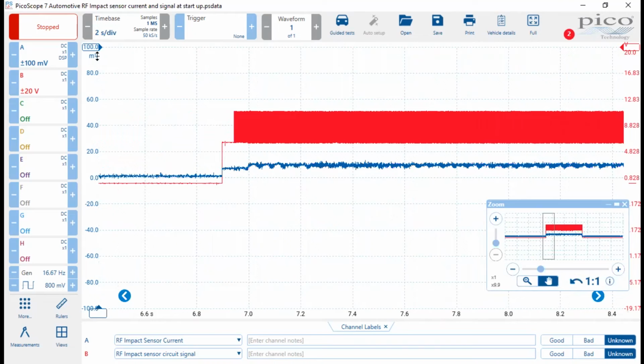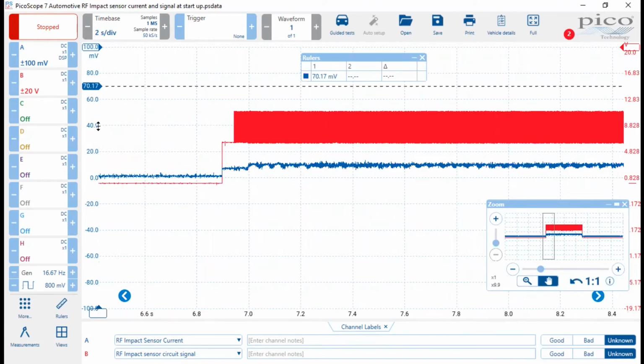Right. So basically, as I explained a little bit earlier, the conversion on our MicroAmp clamp here is 1 millivolt per milliamp. So when we turn this thing on and the computer starts to apply voltage to the circuit, we can see the amperage go up, and it settles in at almost 10 milliamps. So now I know what a good voltage signature looks like, and I know what a good current signature looks like, about 10 milliamps.